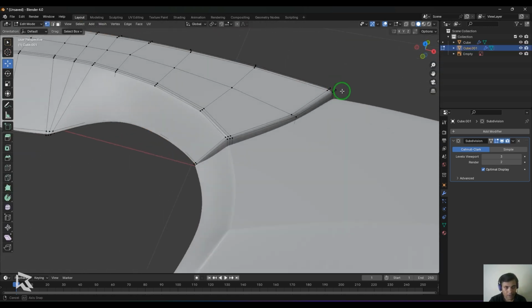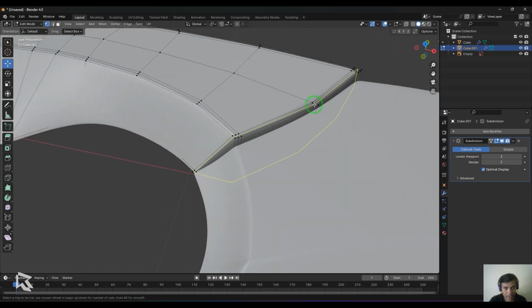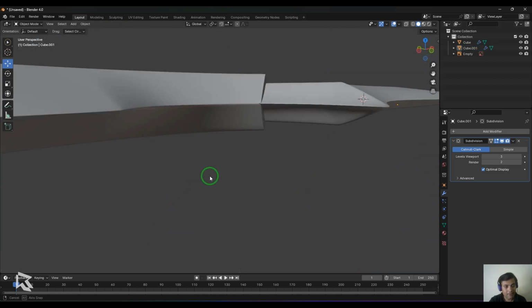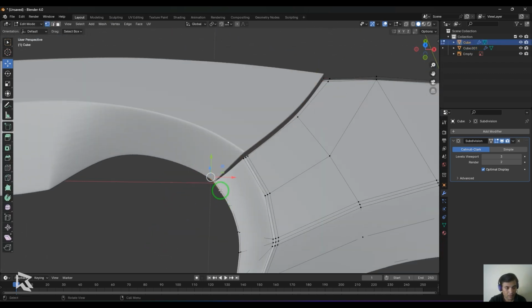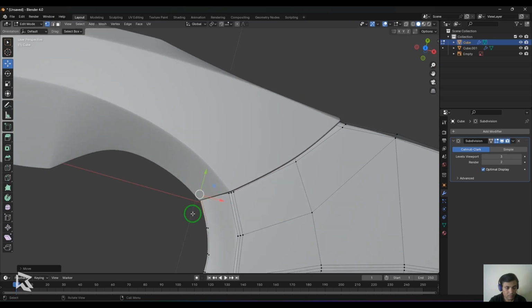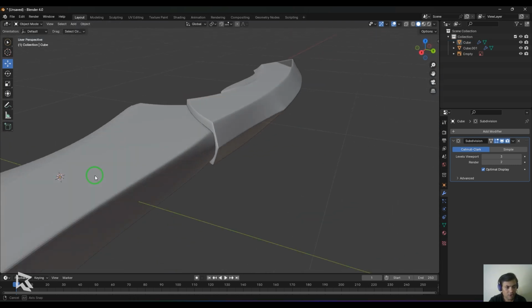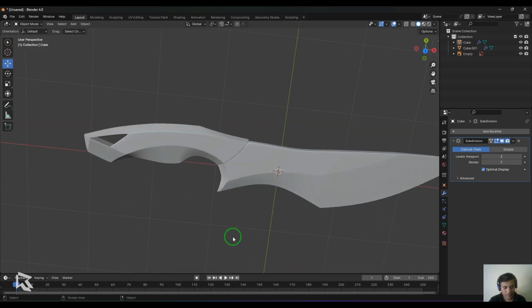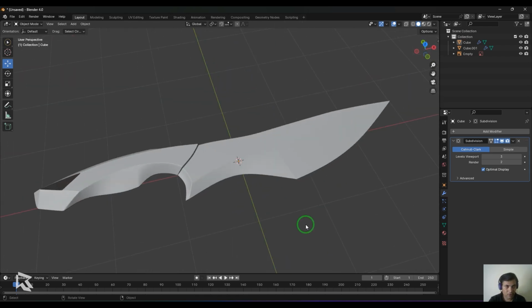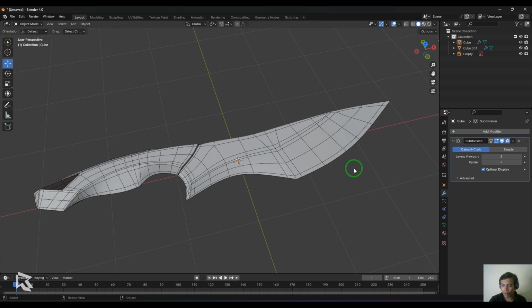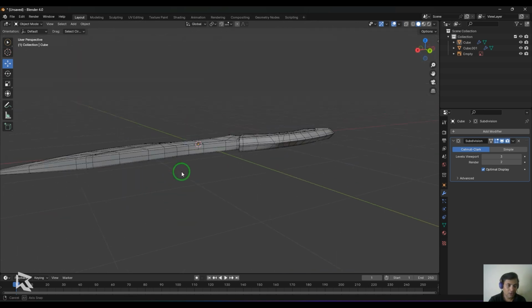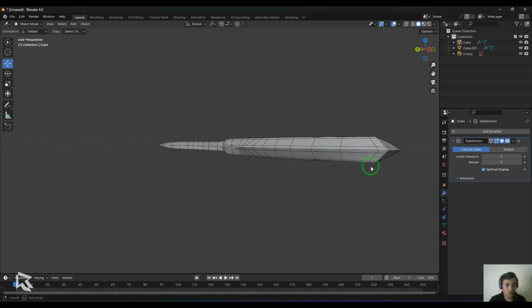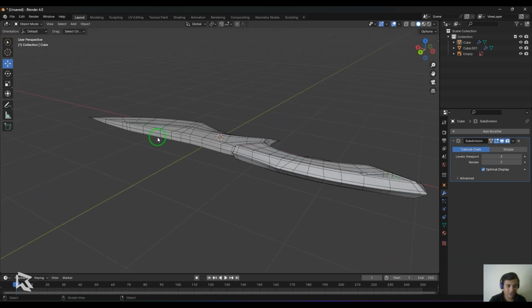You can press Control R and add one more line there, to get a sharp line on this side. So just go a bit minute in this case to handle it in a better way. And this is what we have. I'll just enable the wireframe mode here, and then you should be able to see the way this model has turned out. It looks pretty sharp, and also has that volume thickness on the other side of the model.